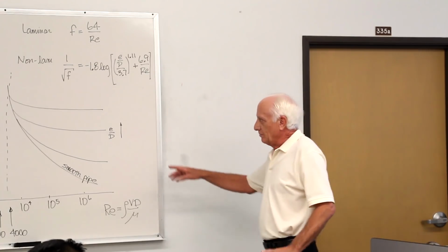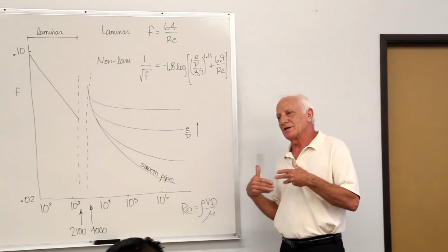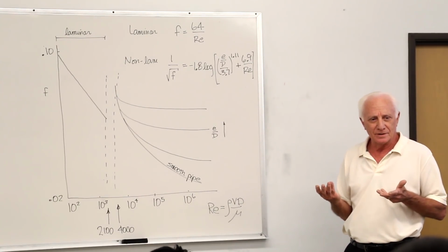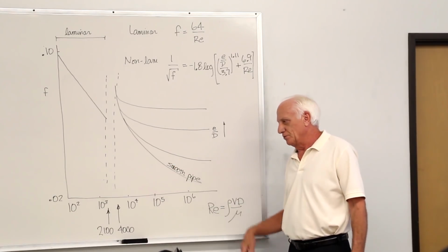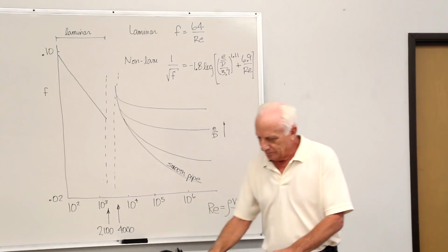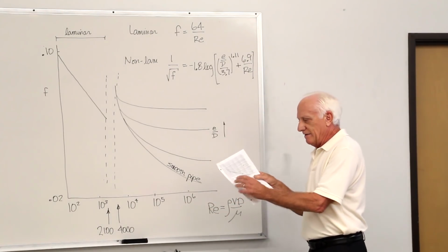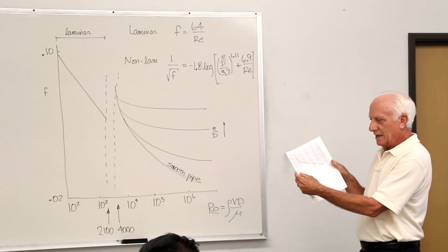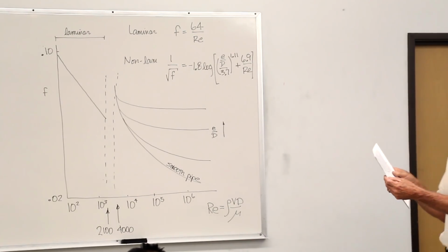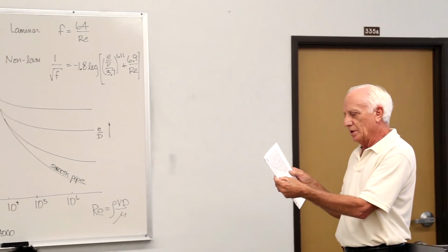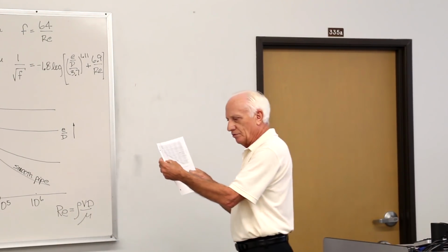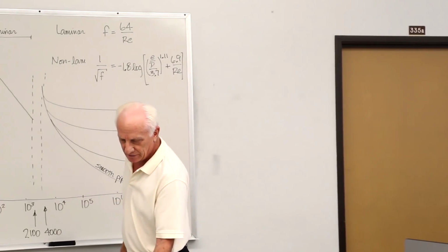If it's a smooth pipe, the roughness is 0, we assume. So for instance, like a PVC sprinkler pipe, very smooth to the touch, slippery almost to the touch. We can approximate that as a smooth pipe. E is 0 for that. And on the Moody chart I gave you, there's a little legend there which has different roughnesses, values of E in both SI and British gravitation. Riveted steel, concrete, wood, cast iron, galvanized iron, wrought iron, drawn tubing. So you have a whole selection of different pipe materials that you can get the value of E for.